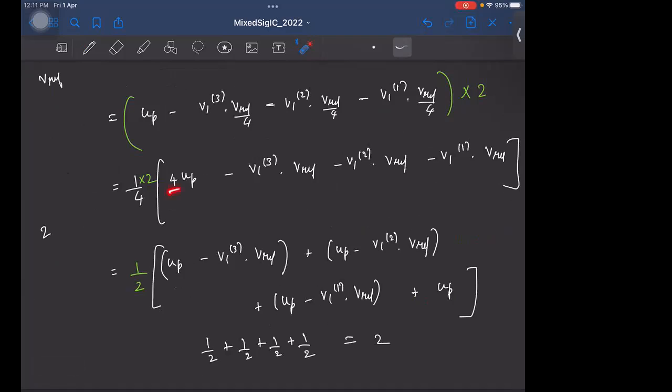So here I'm multiplying and dividing by 4, and had only 3. But for a 3-bit ADC, you'll have 7 such thermometer bits, so we'll multiply and divide by 8. And the gain you want is 4. So the gain for the individual branch will still be half.